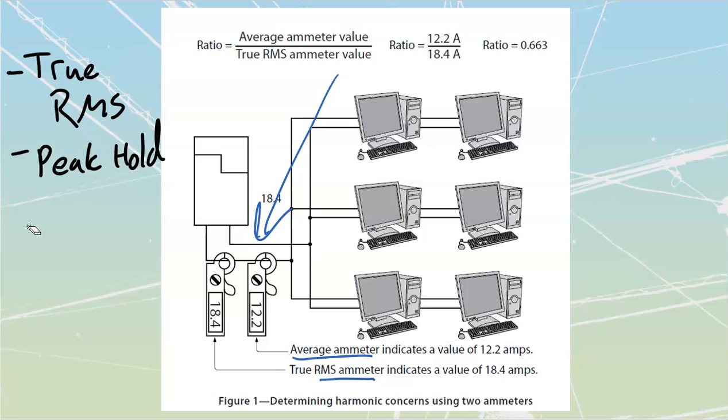Okay, yeah, I think that's as far as we want to take this one over here with the crest factor and all that other stuff. When you're going through, you're going to check voltages, you're going to check currents, making sure everything is balanced. As soon as you get an unbalanced voltage or an unbalanced current, then you are going to have to stop and say, is this going to be acceptable down here?